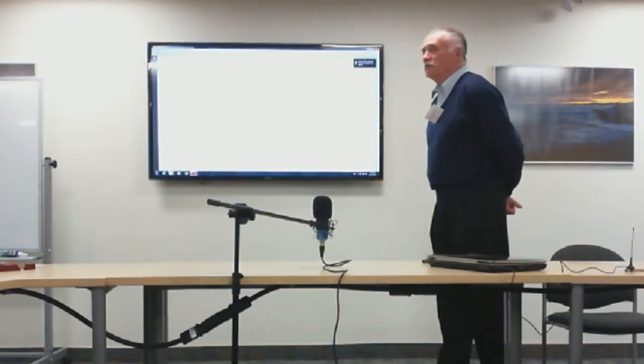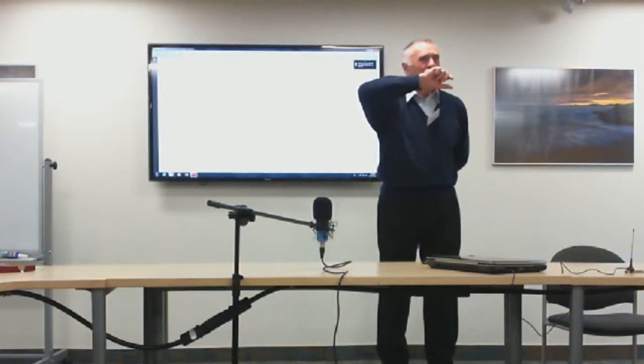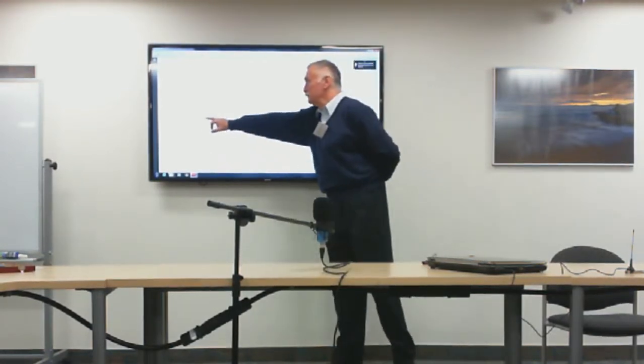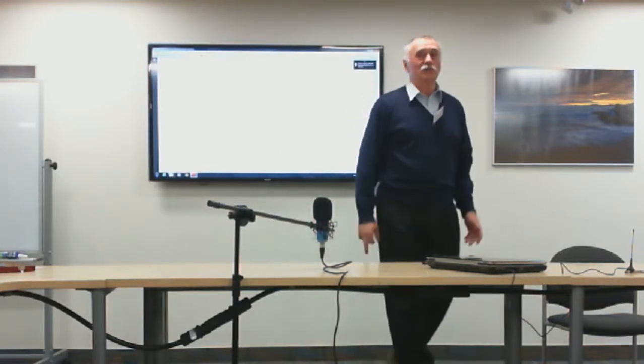And then you know that there are modes again. In CW, you press the key to transmit. In AM, you select AM, you are sending the carrier away. But as you talk to the microphone, you put power into the sideband, so your power increases. If you select FM, by selecting FM, you instantly transmit. Say you turn up the power dial on your radio. In FM, you instantly transmit 190 watts if you draw 250 watts power from the power supply. And that is well within our limits.